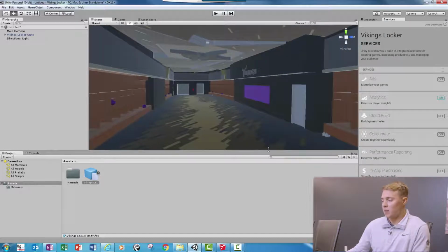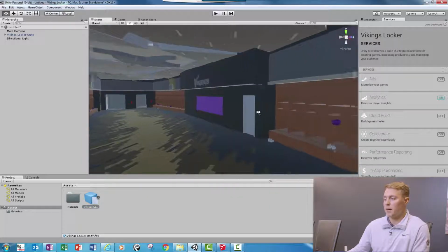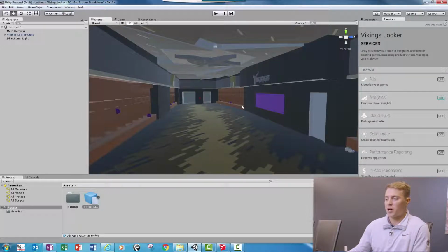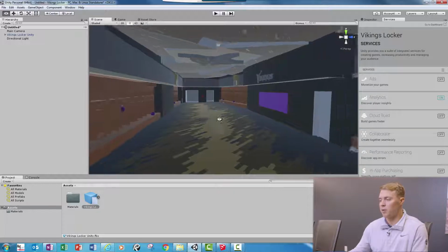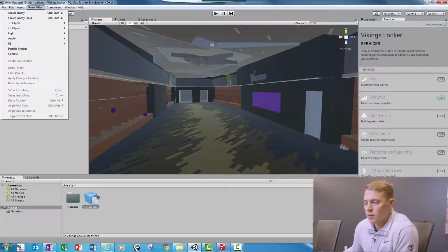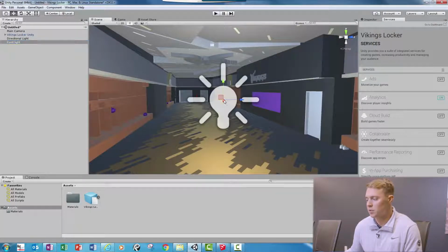So now within Unity, this is really where you can see that all the materials have come in, but there's really no lighting. You can also see that the materials are all pretty flat. So this is where I would go in and select different materials and add bump maps, bump up reflections, or add some glossiness to whatever material I'm working with. But just for a little walkthrough, I can drop in a couple of different point lights and spotlights, just to show.